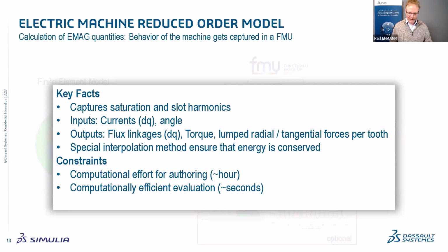It is energy conserving. And what it brings you, sure, the authoring takes some time, depending on the resolution and on the machine you have at hand. However, it is well scalable. Each operating point to simulate can be sent to a cluster, and then you can author this FMU quite fast. But what you win is at the end, you have a really fast model in the system domain. So being able to create controls and run them in seconds instead of hours, as you would with full transient co-simulation with finite element.